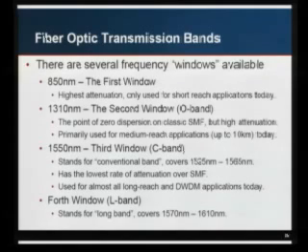The third window is the 1550 window. And there's a band around that called C band, stands for conventional band. It covers 1525 to 1565. This is basically the lowest point of attenuation over single mode fiber. So if you want to go the maximum distance, you need 1550. The difference between 1310 and 1550 on modern fiber is not quite a half the rate of attenuation on 1550, but it's pretty close. And basically, C-band is the range that's used for all long reach and DWDM today.